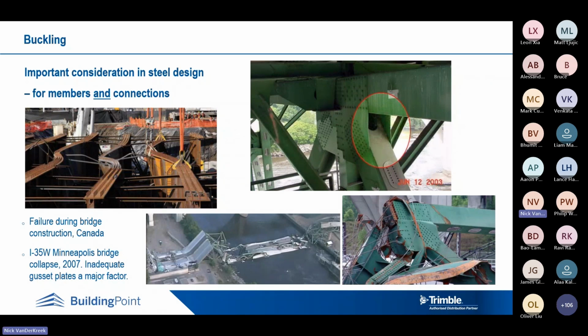In supporting IDS Statica with our various customers for a number of years, sometimes I see quite slender elements included in the design. And so the buckling analysis is something that I talk about and suggest, and I think we need to have somewhat of a focus on buckling because we are, as engineers designing with steel, quite highly tuned and aware of the need for checking buckling for member design and frames and so forth.